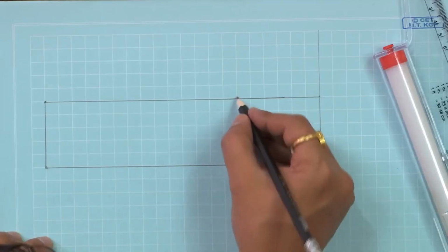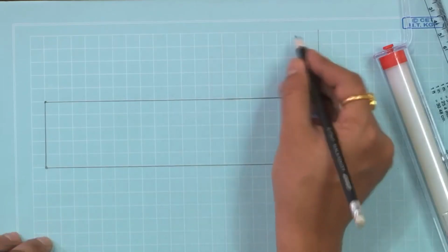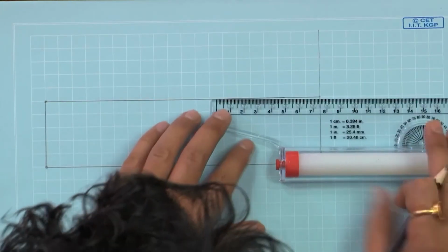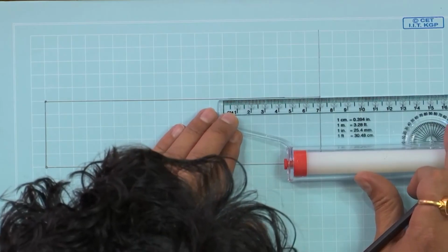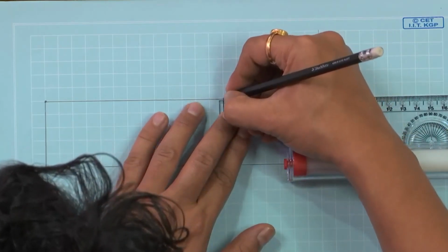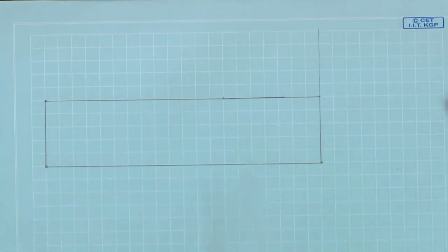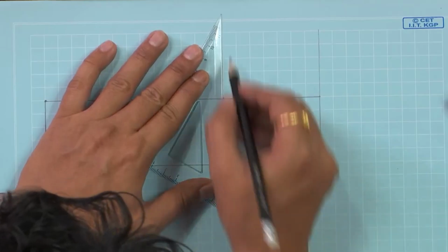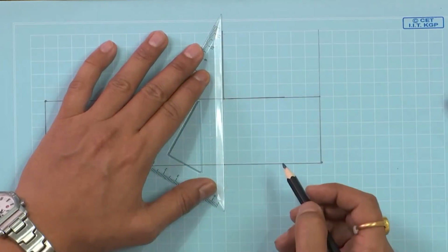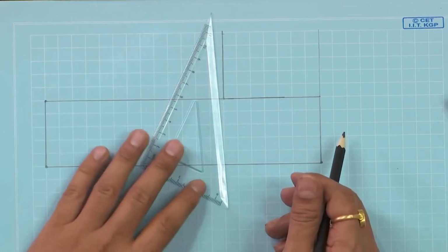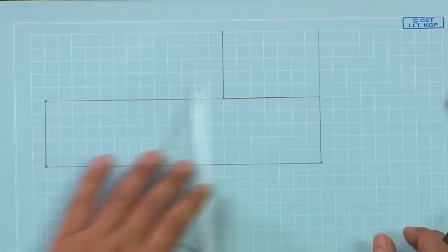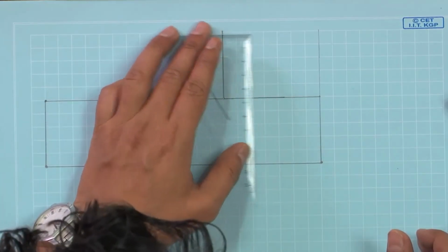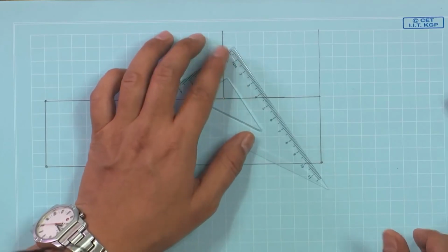And we would like to construct a semicircle, a cylindrical portion, which is supposed to be 70 units from here. So, from here, at 70 units, we have to construct a vertical line. At 35 mm we have this circle. So, locate 35 mm from here. That is also especially from the center it is passing.